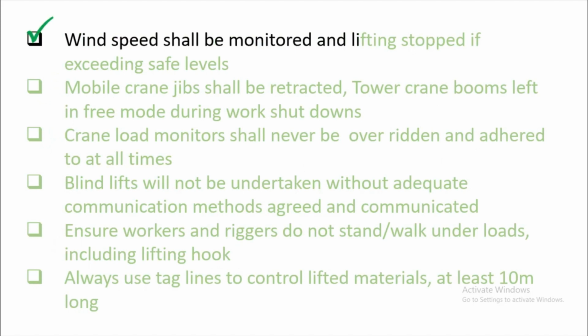Wind speed shall be monitored and lifting stopped if exceeding safe levels. So when you are doing the lifting, as a lifting supervisor, you should always check the current wind speed at every location of your cranes. For example, you have 5 cranes on the site.